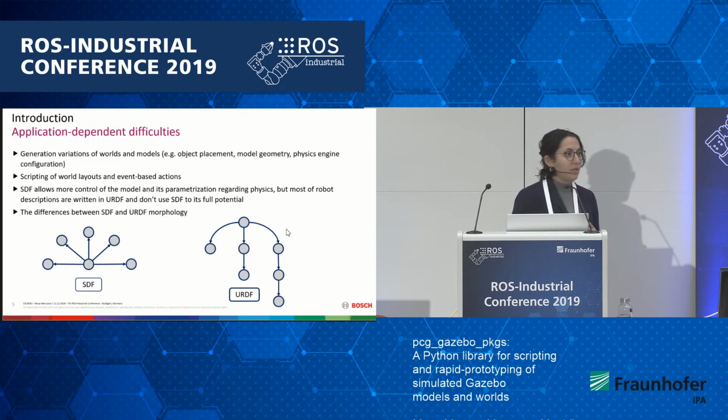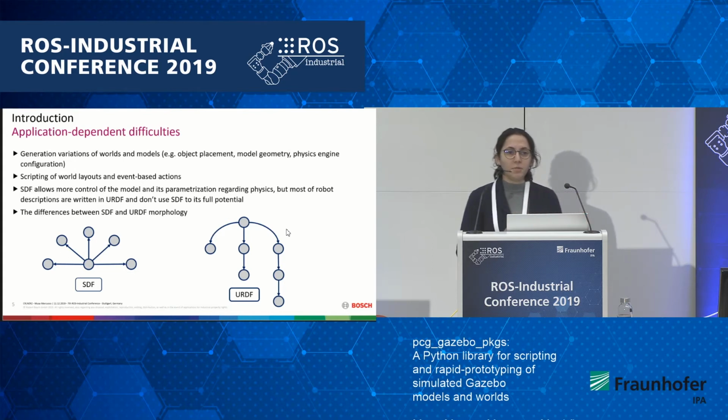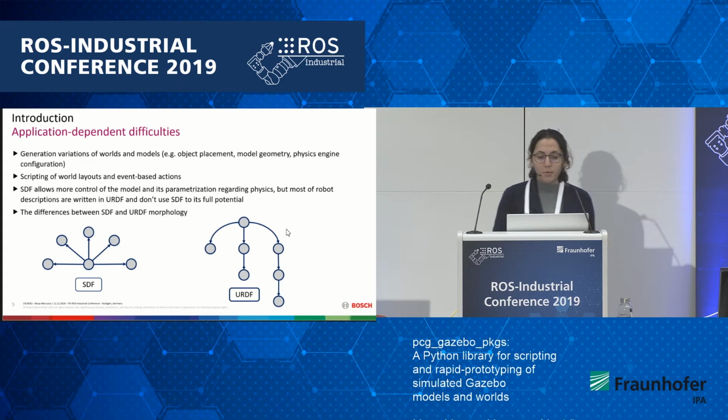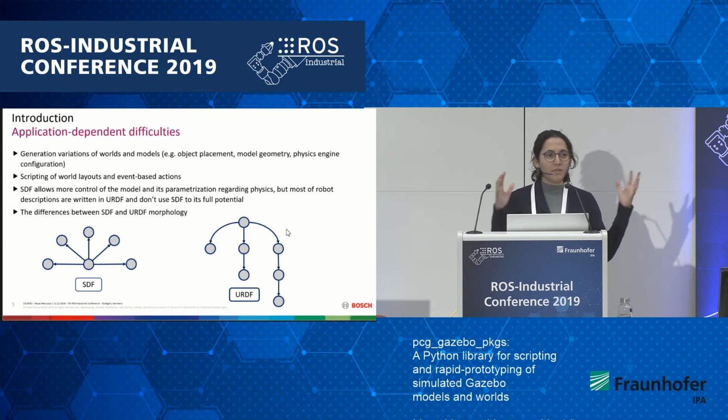Another thing is that, since we're talking about ROS here, robot descriptions are usually written in URDF, but for simulation purposes, SDF is much more powerful. The problem is, one of the problems that we had that might lead to people not choosing SDF to write the robot description, so their physics parameters are described in more detail, is strongly related also to the proposal for SDF 1.7, because it's harder if you have everything described with respect to the model origin instead of being relative to another one.